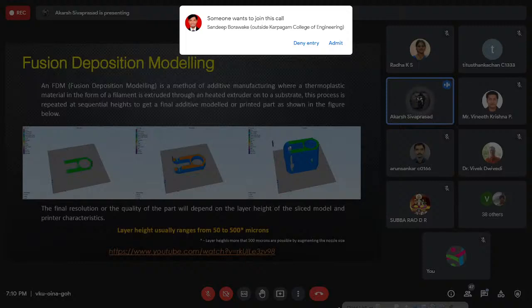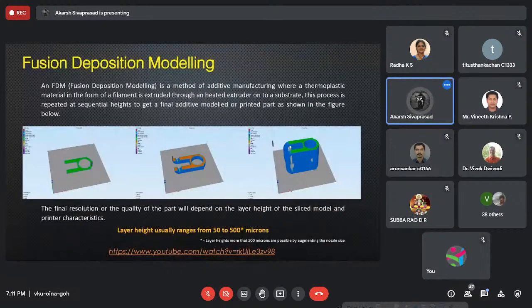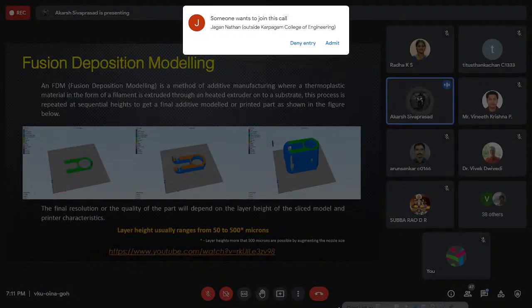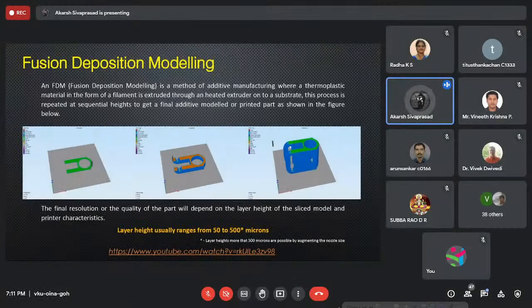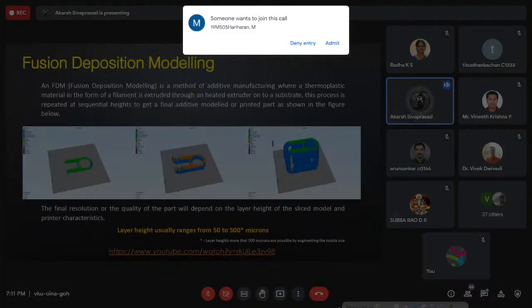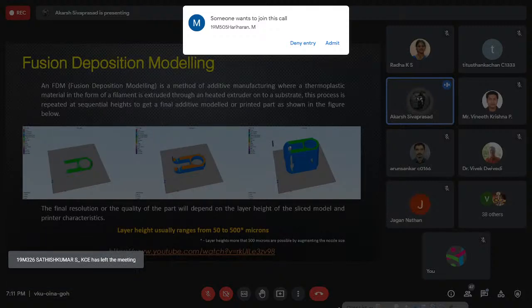So to put it into perspective, the XY plane is on the build platform, where from the bottom left to the right is X and to the top is Y. If you have a knife edge in that orientation and you want to print that, you're extruding plastic through a round nozzle of X diameter, usually 400 microns. To build a knife edge, you have to accelerate in one direction, then decelerate, and then accelerate in the other direction. So no matter what you do, you can never get a sharp point.